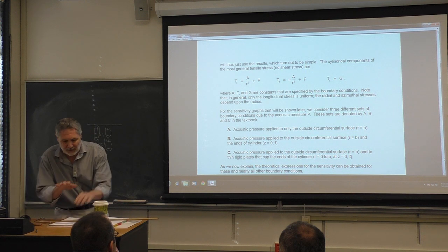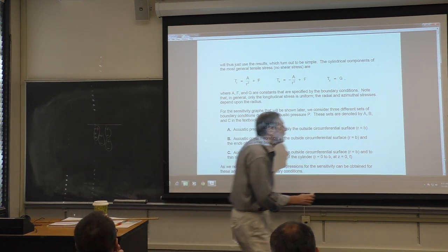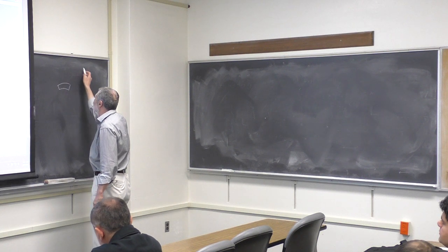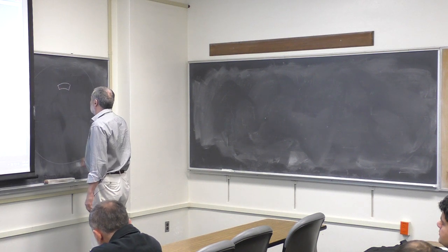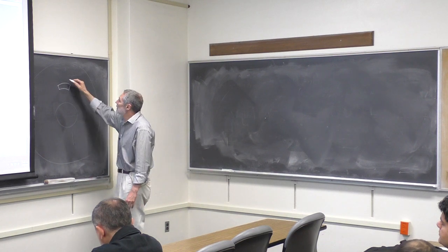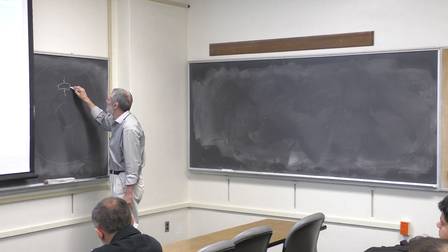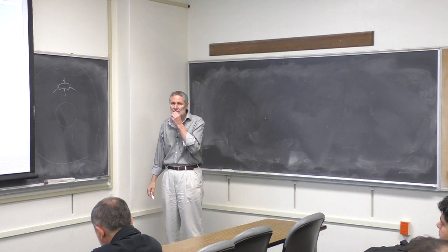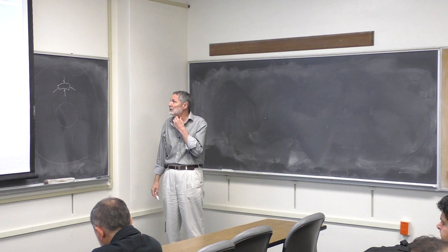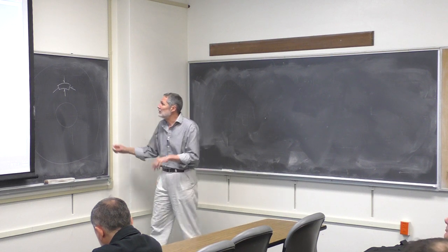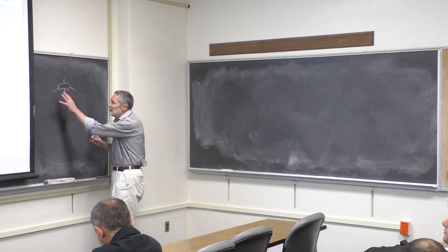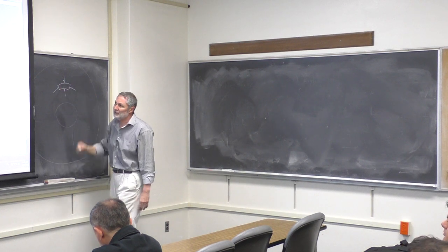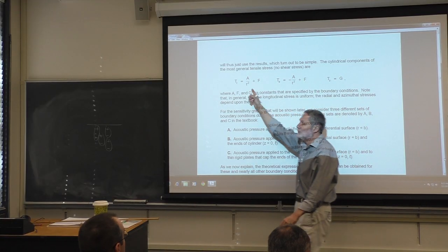So because of the radial geometry, if you look at a little element here, now this is just supposed to be a little element of this bigger cylinder here. All of these stresses are going to have to balance, all right? And there can be no torque too. So it's very natural to suspect here, because of the radial geometry, that there's going to be a radial dependence. And here it comes in right here as 1 over R squared.